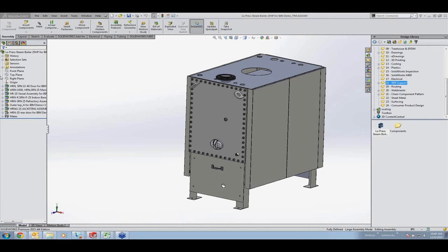All right, I can also insert components to my cable tray routing, just like I did in the HVAC routing. So in this case, I want to create the cable tray cross. There's only one configuration available for this component. Just drag my line out here. This is all dynamic, so it updates dynamically here. Get back into my line tool.